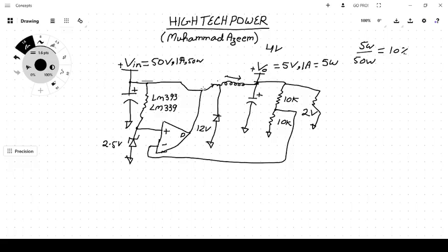So when the transistor is off, that current which was lagging in the inductor would go through the output load, and from the ground path it would find the route through the diode, and it would forward bias the diode, so it would complete its path through the diode, instead of going through the input circuitry and destroying the input transistor.